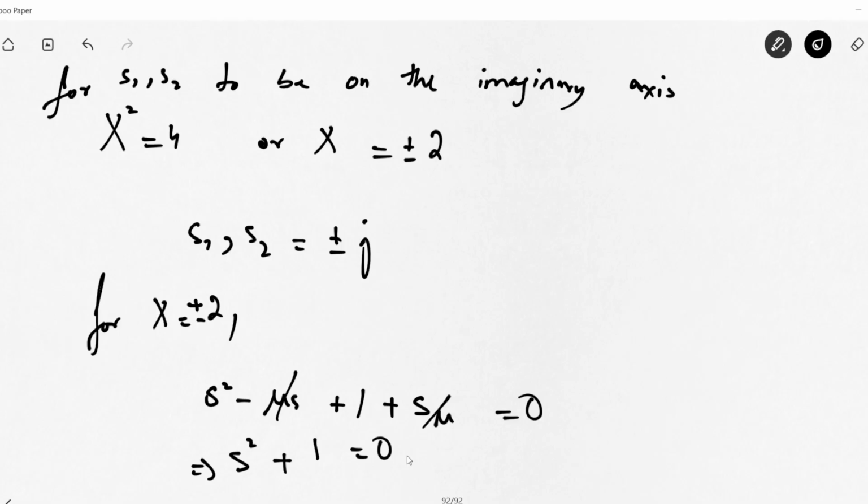So for this system, omega n is equal to under root of 1, that is equal to 1. So this system will exhibit the property of limit cycle for x equal to 2, and this shows how we can find out limit cycle in the system. If any condition does not meet the requirements for the undamped response, then we can say that this system will not show the property of limit cycle. But in this particular case, we are seeing that a limit cycle will exist in the system. This is how we can examine the existence of limit cycle through the describing function method.